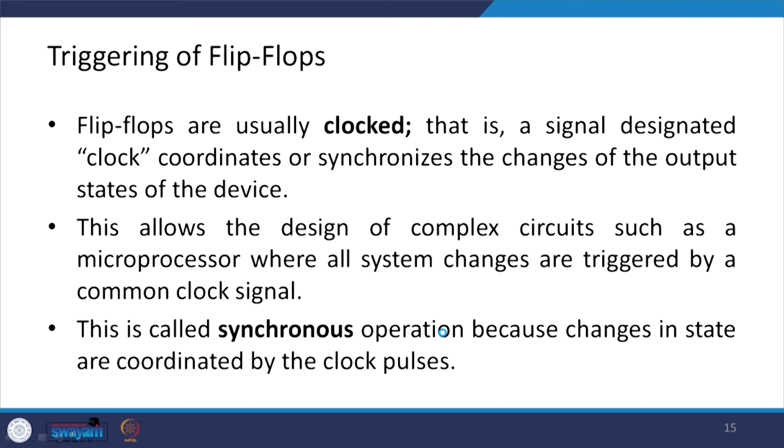Then, triggering of the flip flop. When should the change of input from S to R be done? This is what we call triggering. Flip flops are usually clocked, that is, a signal designated clock coordinates or synchronizes the change of the output states of the device.